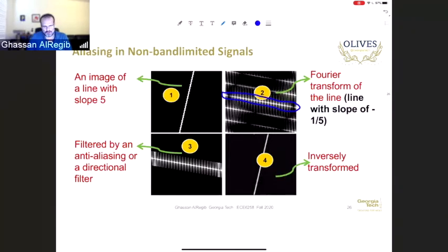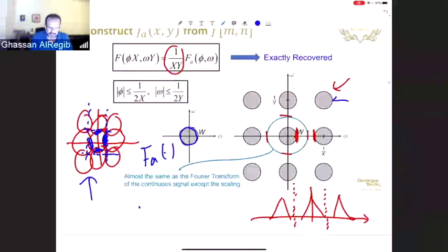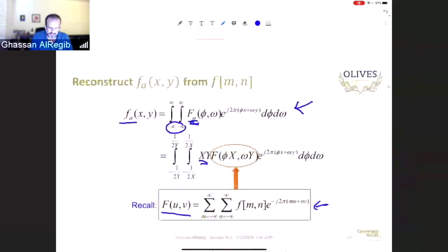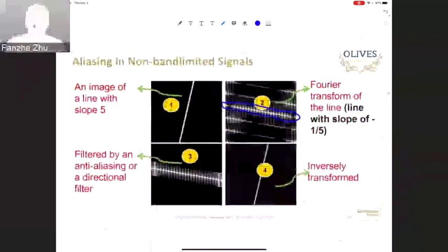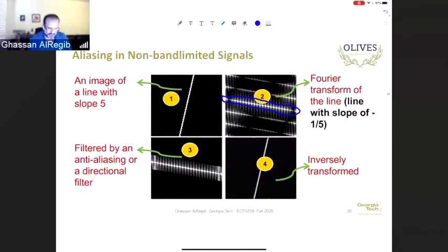However, if you look carefully, we have more copies of them. These are the copies of the spectrum that are obtained from the aliasing effect, which is the same as what we have here. This aliasing is happening because of, and there was a question about what we mean by high frequency, these transitions, this sharp transition between 0 and 1, they really contribute to the high frequency.